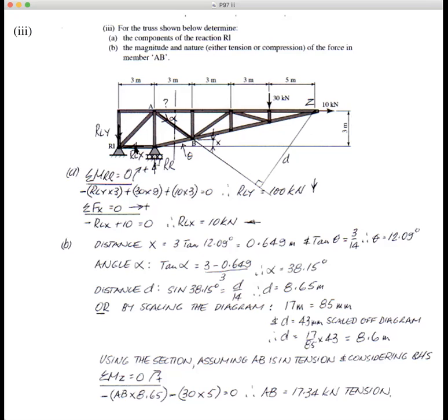To find this force here, that has to equal any other horizontal force there. So obviously that's got to equal that 10, and it's got to go in the opposite sense to that. And this is how you set it out. Sum of the forces in x equals 0. X is the horizontal component, so we've got RLX minus, which is going negative. I've put it negative because I could see that's positive, plus 10. So we've got RLX equals 10. Positive answer, so therefore that's correct.